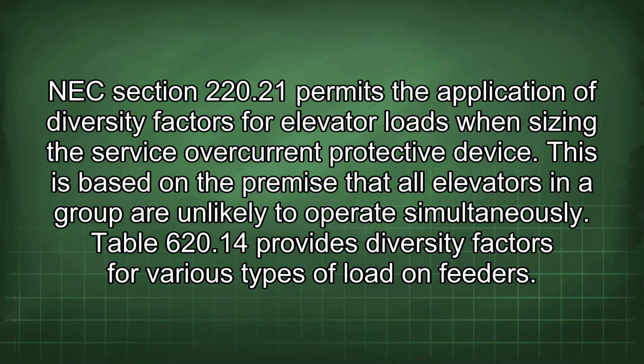NEC Section 220.21 permits the application of diversity factors for elevator loads when sizing the service overcurrent protective device.